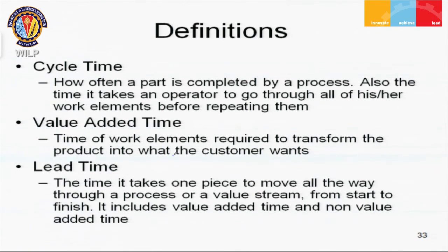The lead time is the actual total time that it takes to move one piece all the way through the entire value stream from the start till the finish, which is the time from the time that it arrives, sits in your incoming stores, moves through all the manufacturing stages, and then finally leaves from your dispatch gate. And this would include both the value added time as well as the non-value added time.